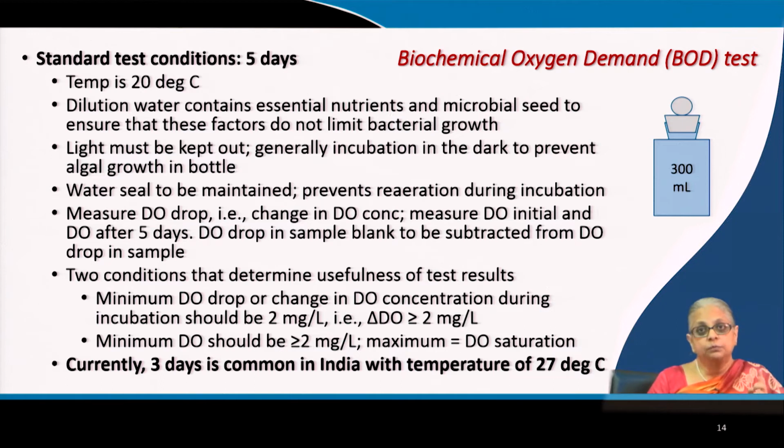On the other hand, in municipal sewage, we don't need to add microbial seed because sewage has millions to billions of cells per ml. So no need for adding other seed. There is a sufficient native population of bacteria that will be capable of degrading the organics in the wastewater. So like I said, this is the first part of the test.